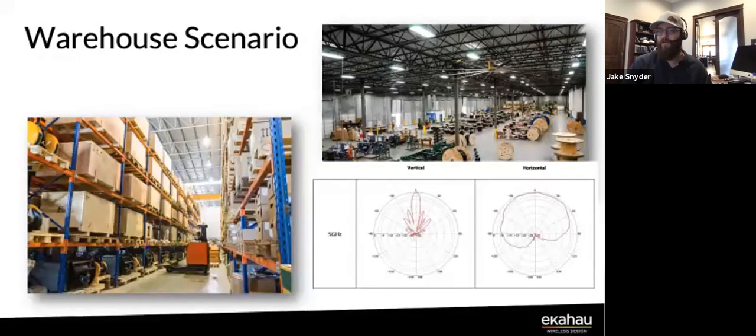The only thing I would caution folks is people start getting crazy with high gain directional antennas in warehouses, and they forget that 40 feet's a good distance. You get beyond 40 feet, to 50, 60, 70 feet, and you start getting your butt kicked by regulatory bodies. If you're in the US, the FCC is going to cap how much transmit power you can use, and it's not linear. They may say you can't transmit as loud because of all this gain.